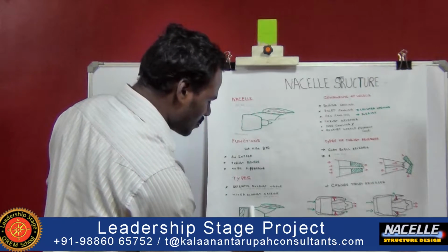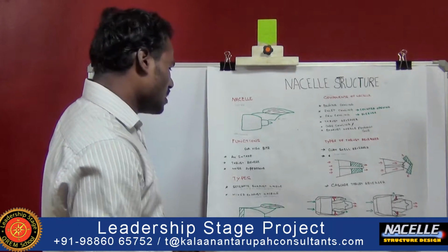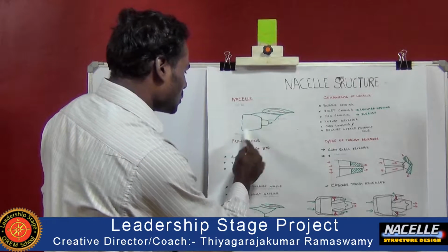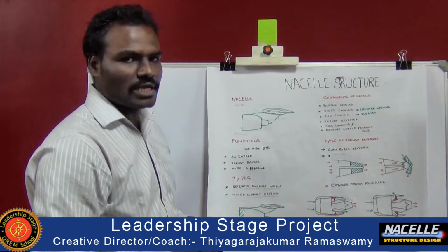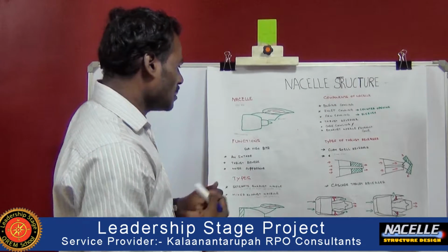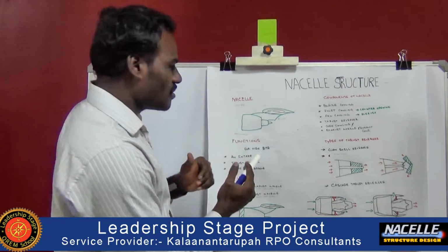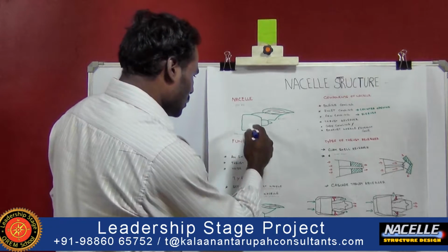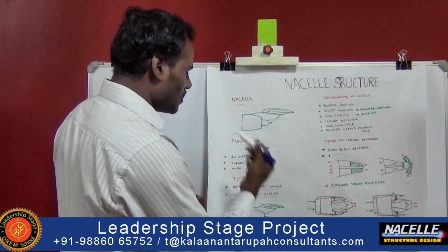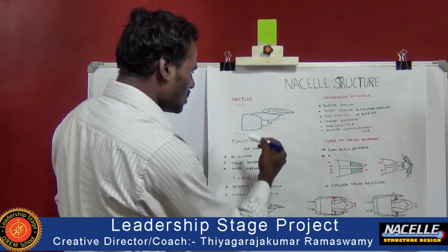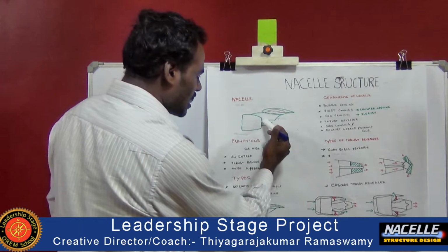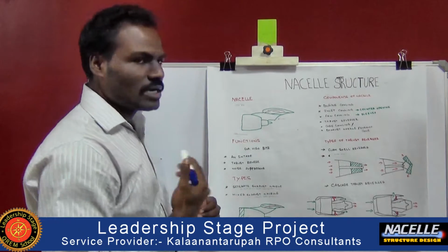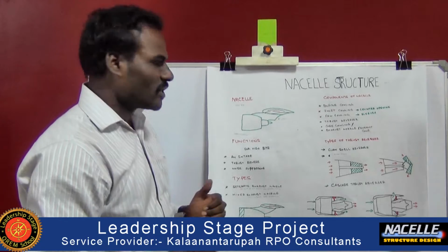And this is the diagrammatic representation of a mixed exhaust nozzle, whereas here the flow of the air is separated, so that some of the process will be carried out at this area, and the flow of the air from the fan is subjected to the engine area at this area, so there is a separation of flow which results in a better performance of the aircraft.